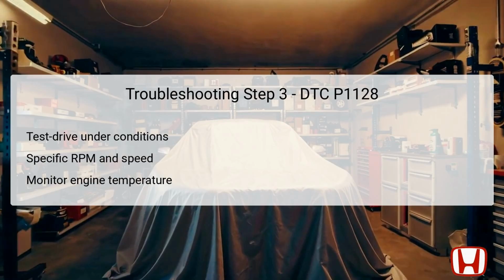Make sure the engine coolant temperature, as indicated by the ECT, engine coolant temperature sensor, is above 158 degrees Fahrenheit, 70 degrees Celsius. The engine speed should be maintained between 1200 and 5400 RPM, with the vehicle in drive for an automatic transmission or third gear for a manual transmission. Furthermore, accelerate the vehicle to speeds between 16 and 31 miles per hour under half throttle.